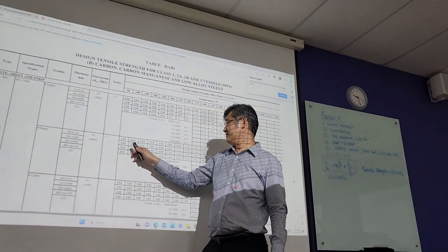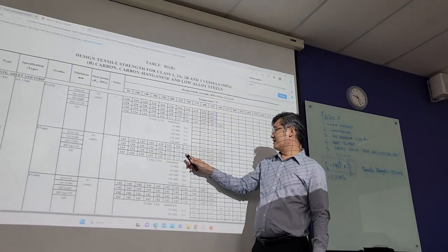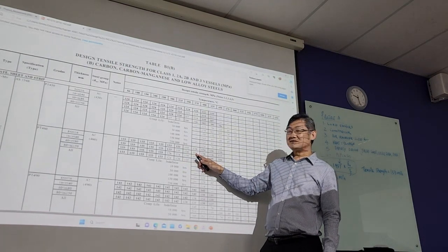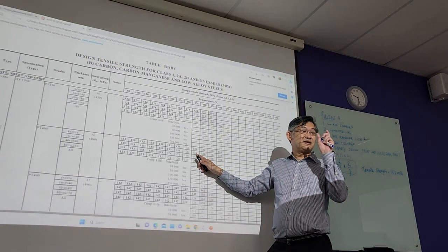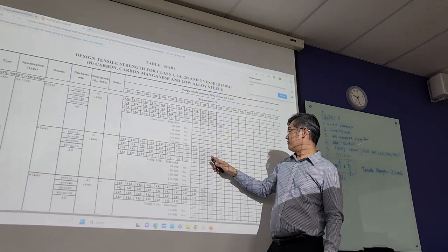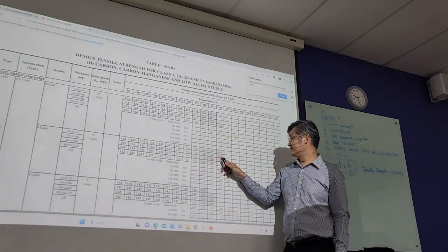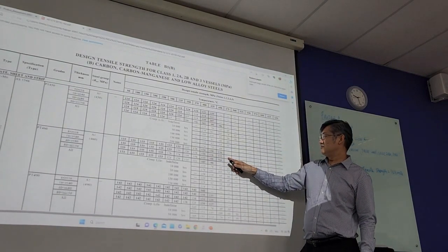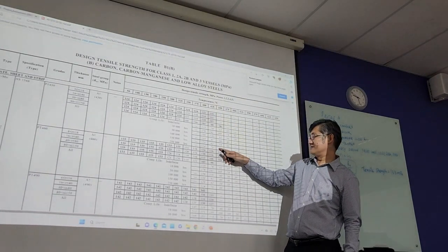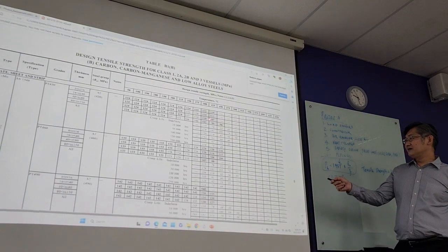You can see it deteriorates until 350, where it starts to decline, 133 to 128. Then at 375 it becomes 124, meaning the material weakens, because the stress it can withstand is getting lower. After that 120, 116, and at 450 about 112. After that no more, meaning the highest temperature will be 450 degrees Celsius. More than this, there is no value already.